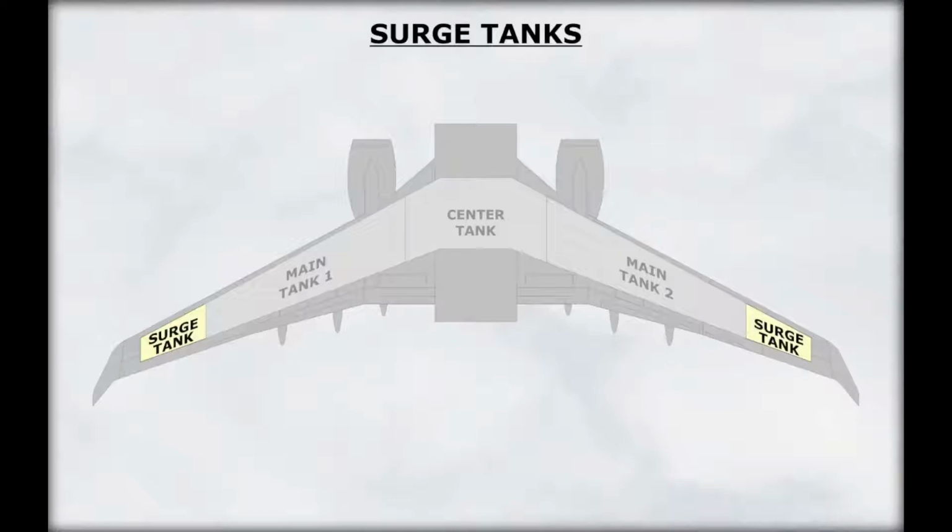2 surge tanks prevent the excessive buildup of pressure within the tanks. These surge tanks are located outboard from each wing fuel tank and vent through a single opening under each wing tip. The fuel accumulates in the vent tank and returns to the tanks.